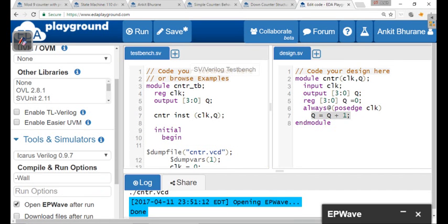This is what is called behavioral modeling of a 4-bit positive edge triggered up counter. Now here I didn't specify the flip flops. Here you can't select what kind of flip flops to use, and you can't select whether it is a ripple counter or a synchronous counter. For that purpose, we'll have to go for structural modeling. So once you are done with this, go for structural modeling of a 4-bit ripple up counter using T flip flops. Now that's a complete specification for structural modeling.